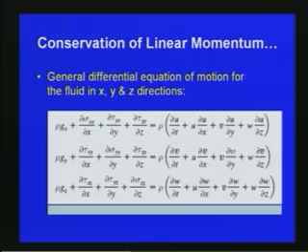for Euler's equation or inviscid flow, the shearing stresses are 0, so the shearing terms have gone from the left hand side of this equation, and then we have the normal stress components.